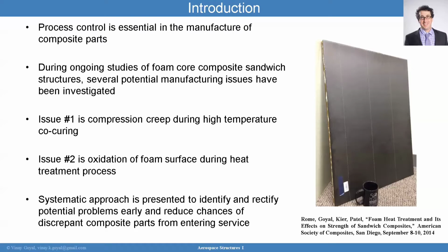Now, there are a couple of reasons you want to do testing, and I'll focus on composites because that's where we are right now. You want to understand the properties of the material you actually have, not the material that another lab or another manufacturer made. It might be okay in the initial design iterations to get close enough, but by the time you put a part into service, you need to know what the real properties of that part are.